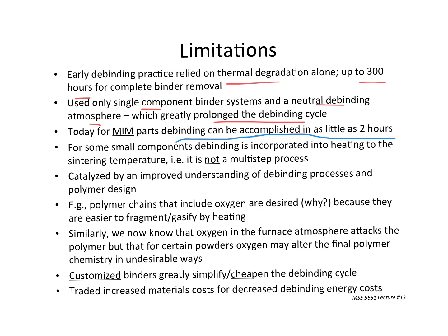For some small components, and we're talking pretty small, debinding is incorporated into heating to the sintering temperature. It is not necessarily a multi-step process. Sometimes when things are tiny, diffusion distances are small, and the binder can come out without really damaging the part.